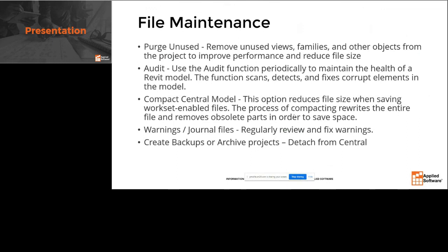settings and configurations that maybe just haven't been used yet, depending on where you are in the project, like filters, view templates, that kind of stuff. It's not going to remove anything that's already there. So when do you do this? Again, I would purge unused at issues, when you're issuing a check or an update, or at the end of the model, make sure you always purge it out, because you're almost 90% done.